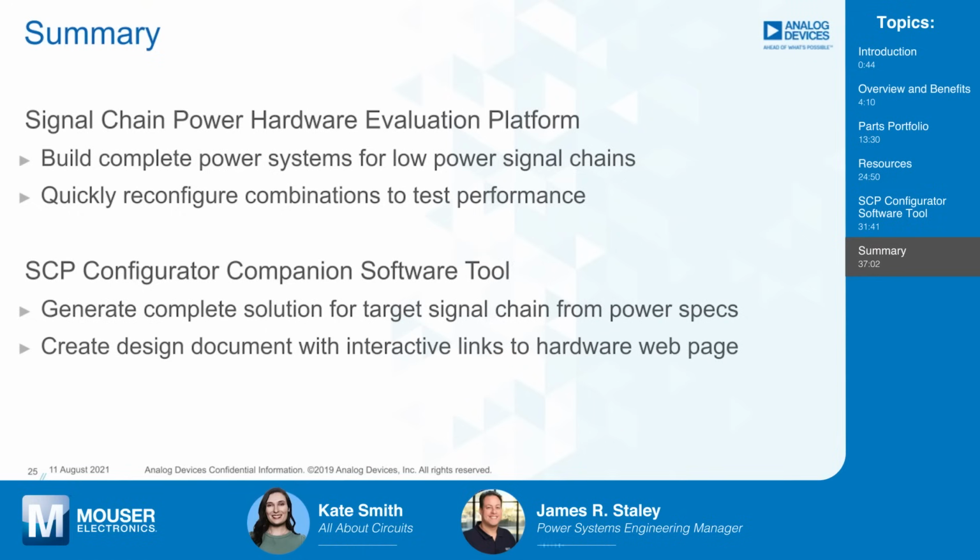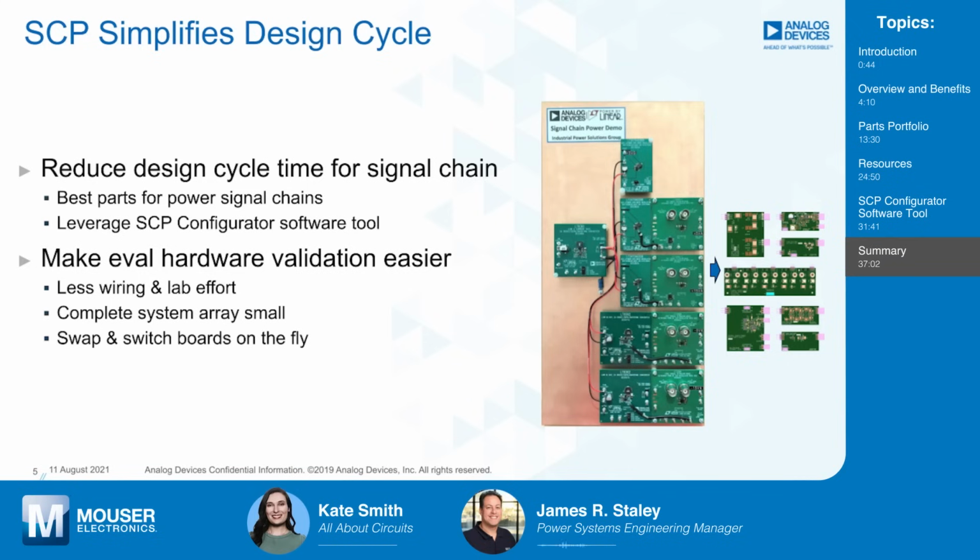So, it's interesting that you mentioned that, because one of the last really high performance signal chains that I did in my days as an applications engineer was shown on slide 5, I believe. There's a picture there. It says giant copper clad. This is yours. And I spent the better part of a day and a half out in the lab modifying those demo boards, putting whiteout underneath their little plastic feet standoffs, and putting them down. So when I lifted them off, I had a place to drill a hole to then screw them all together onto that back plane. I then wired them all up, wired them together. I had to scratch out little bits of copper to make some additional connections and take those boards and modify them. That is shown side by side with the equivalent SCP hardware.